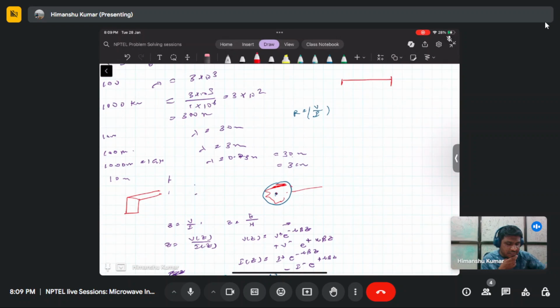But then in the low frequency case, only the series resistance of these wires is important, not the distributed capacitance and inductance which forms in this wire. So if you want to have the transmission of this signal, you don't need to consider any distributed case, especially when you are working with a low frequency. Even for two wire lines you don't need to consider.